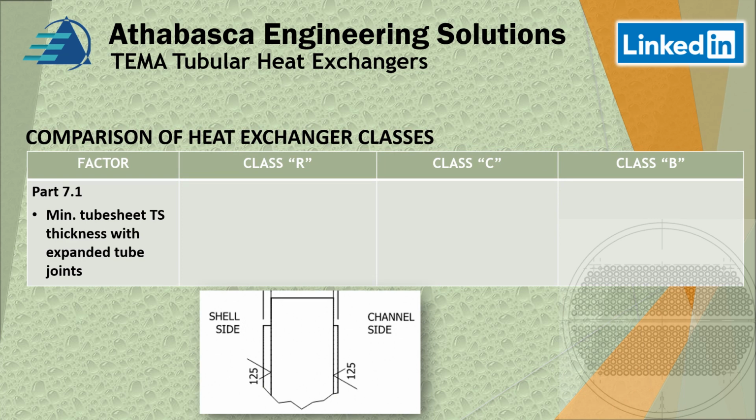Minimum thickness of tube sheets, there are a number of rules. For Class R, the tube sheet must always be at least 3/4 of an inch thick. Secondly, the tube sheet thickness minus the corrosion allowance must be equal to or greater than the outside diameter of the tube. Now there are some relationships between thickness and tube OD.